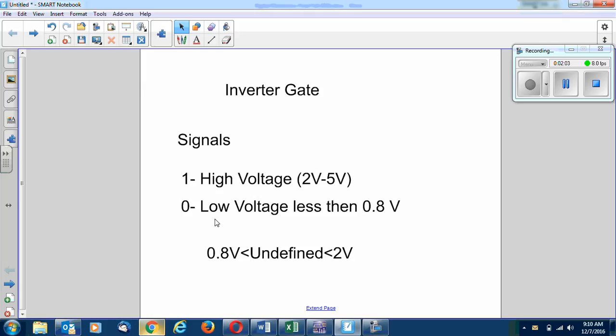Our signals are going to be always voltage. And voltage signals in general, you can encode music in voltage signals, and that will be an analog recording. That's absolutely possible. But we are not doing it like that. So we're just gonna digitize that signal. So this means that this undefined region we have to avoid, because that will completely mess up our circuit.